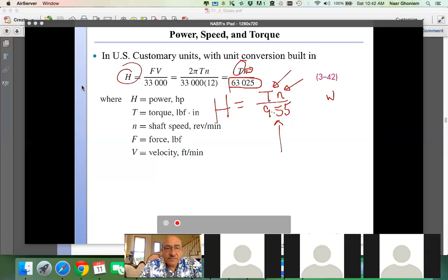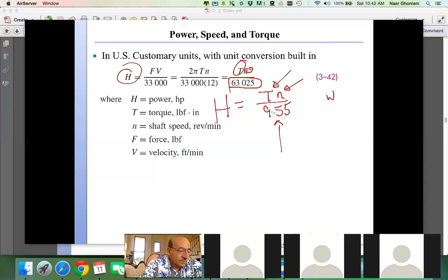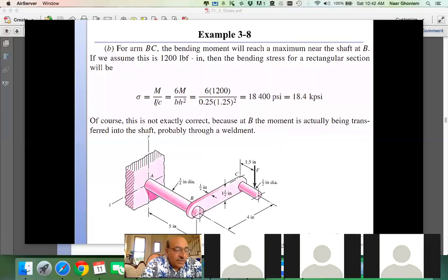Justin, do you have any questions? When determining the tau max with the pressure cylinders, will the longitudinal stress come into play very often? Not in our considerations. That's a good question, because the longitudinal stress for a thin wall pressure vessel is usually half of the tangential, and the radial is usually very close to zero for a very thin tube. But if you have a thicker section, then the sequence of stresses would be the tangential is the highest, longitudinal is the middle, and the radial is the lowest. Got it. Thank you.